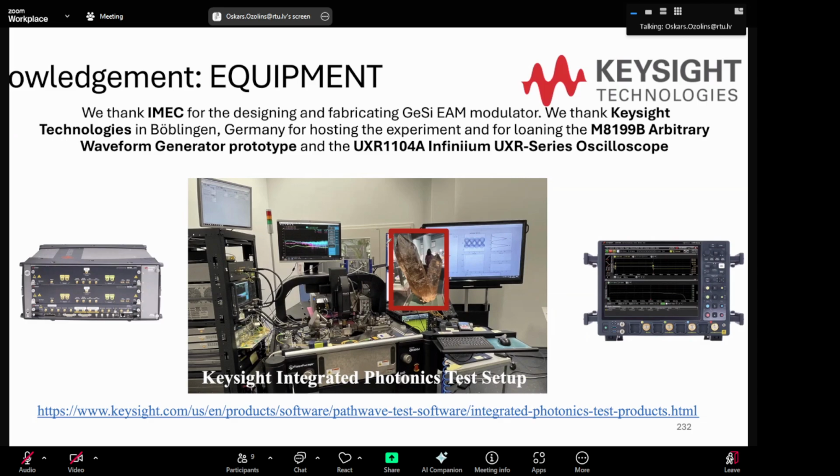So sometimes we test chips we are not allowed to show. That's why I have here this crystal image, which I took in Washington, DC. I was in the Natural History Museum. It was a silicon photonics conference, which happened in 2022, I think. And then I presented the results of a chip which we were not allowed to show. So I put this image here, but you can see that it's pretty high speed on-off keying. I think that time it was 240 gigabits per second on-off keying. So we managed to increase that number quite a bit.